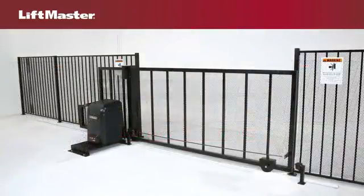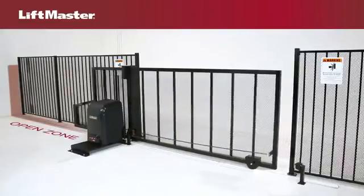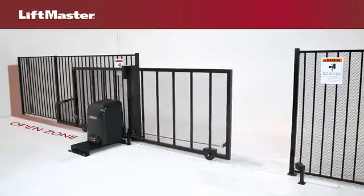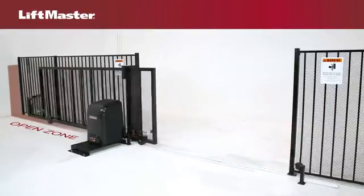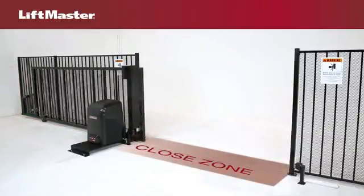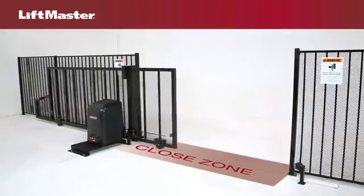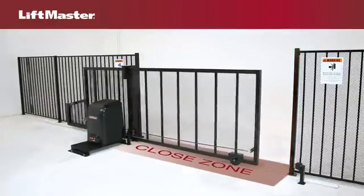Let's look at the entrapment zones related to the open and closed cycles of a slide gate. During the open cycle, the most likely points of entrapment are between the rear edge of the moving gate and any rigid object that the edge may pass or approach. During the closed cycle, the most likely points of entrapment are posts, a wall, or in dual gate applications, the place where the two gates meet.